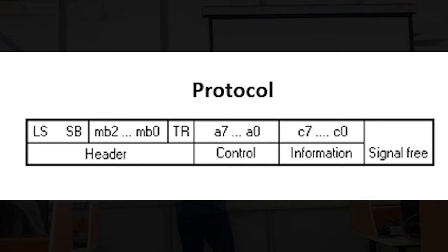So these mode bits decide where the split happens. Is it an 8-8 split? Is it a 9-7 split? Is it a 6 and 12? So this is how the mode bit defines where the split happens, but usually it is 0, 0, 0 itself, right? So 0, 0, 0 means 8 and 8 split. You understand this, right? Okay.